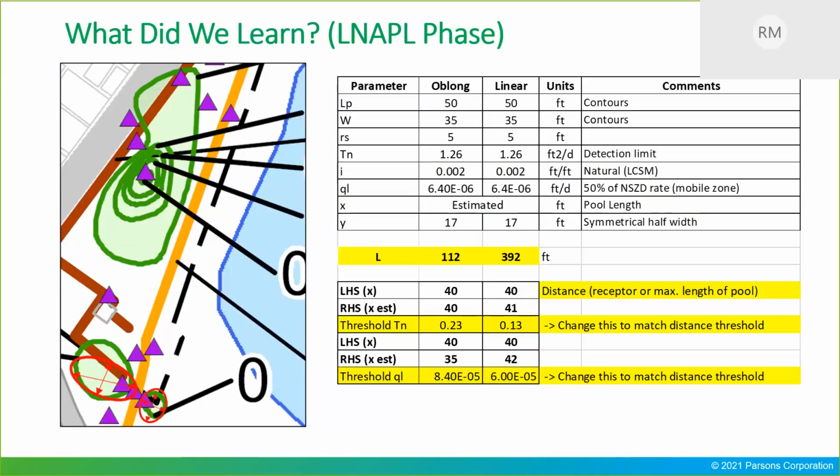We started off with the approximate solution, wherein we know that at long times you essentially get a linear relationship between the migration and the depletion. But bear in mind that the linear approximation assumes your NAPL flux is uniform across your mobile NAPL interval, which is typically not the case, knowing how NAPL behaves. Unless your mobile NAPL interval is relatively small compared to the changes in the gradient, then maybe. Obviously your soil parameters also play a role. But for the most part, the linear approximation is more conservative, or overly conservative.